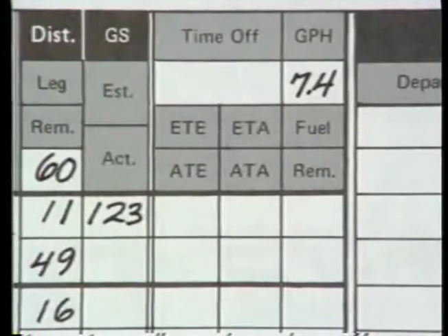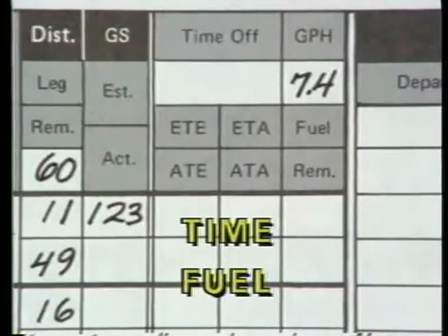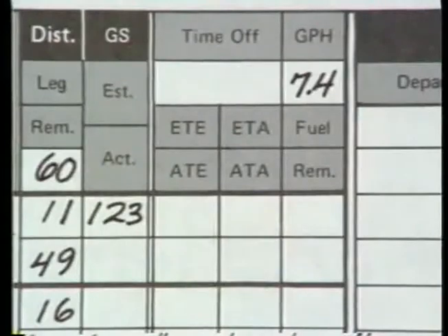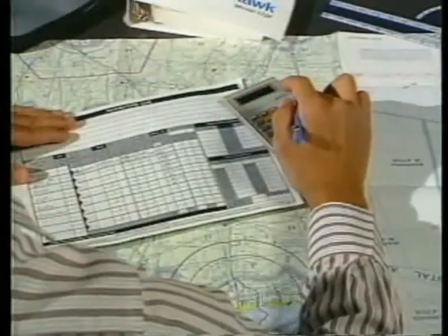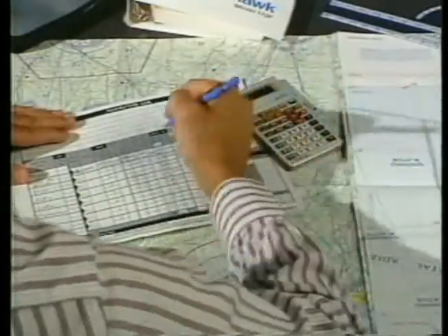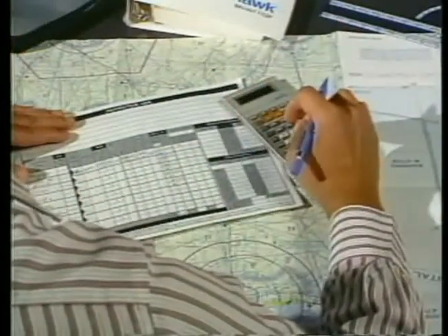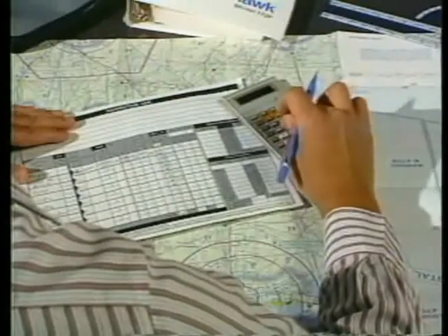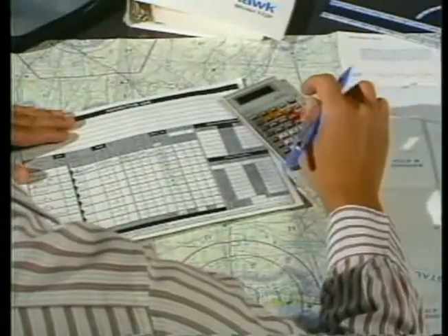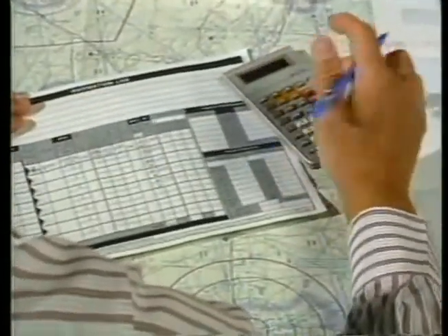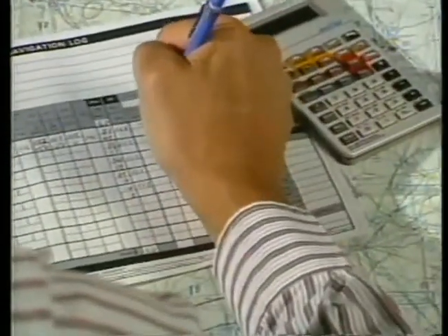As a final step in the route planning, compute the time and fuel requirements for the flight. These are basic time, speed, and distance calculations to find the estimated time en route, ETE, between checkpoints and the total estimated time for the complete trip. The fuel requirement should also include the reserve required by the regulations.